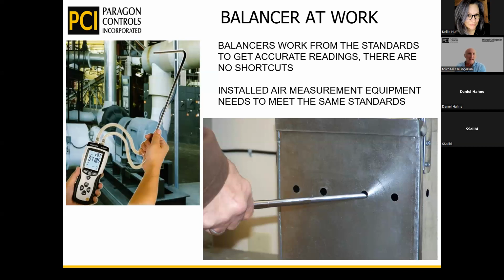And as we know, in the world of VAV, the systems very rarely operate at full flow. I mean, you usually see them flow at 60 or 70% most of the time, and how they're reacting or moving within a duct or an opening could be very different than what it is at full flow.